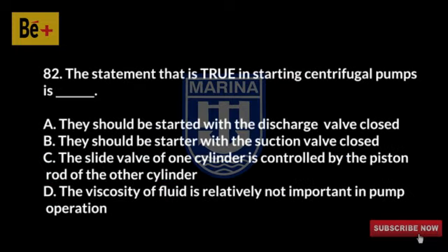The statement that is true in starting centrifugal pumps is: A. They should be started with the discharge valve closed, B. They should be started with the suction valve closed, C. The slide valve of one cylinder is controlled by the piston rod of the other cylinder, D. The viscosity of fluid is relatively not important in pump operation. The answer is A. They should be started with the discharge valve closed.